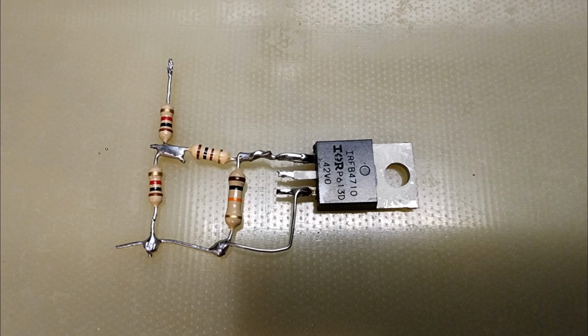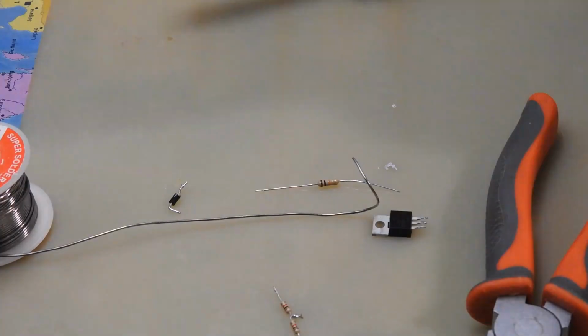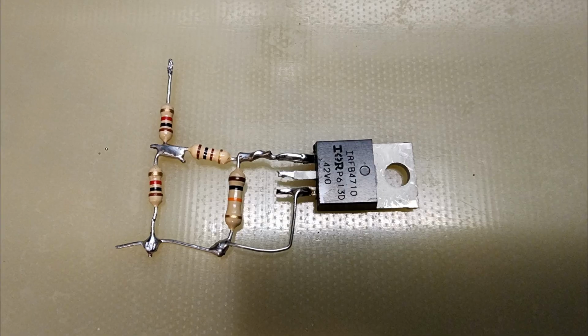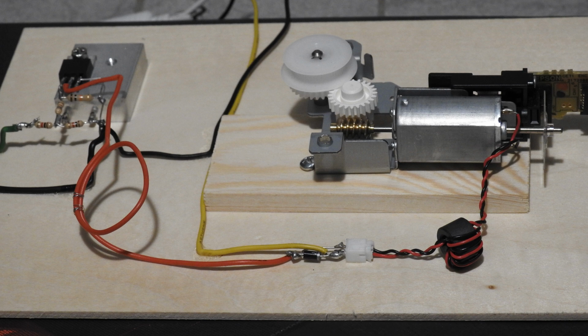Let's speed up and build the motor power stage using the IRFB4710 transistor. Now, we will wire the power stage with the 12-volt DC motor. This type of DC motor is commonly found in printers. We add a heatsink to the IRFB4710 to help dissipate heat. However, in this project, there is no significant risk of overheating because the transistor is largely oversized for this small motor.